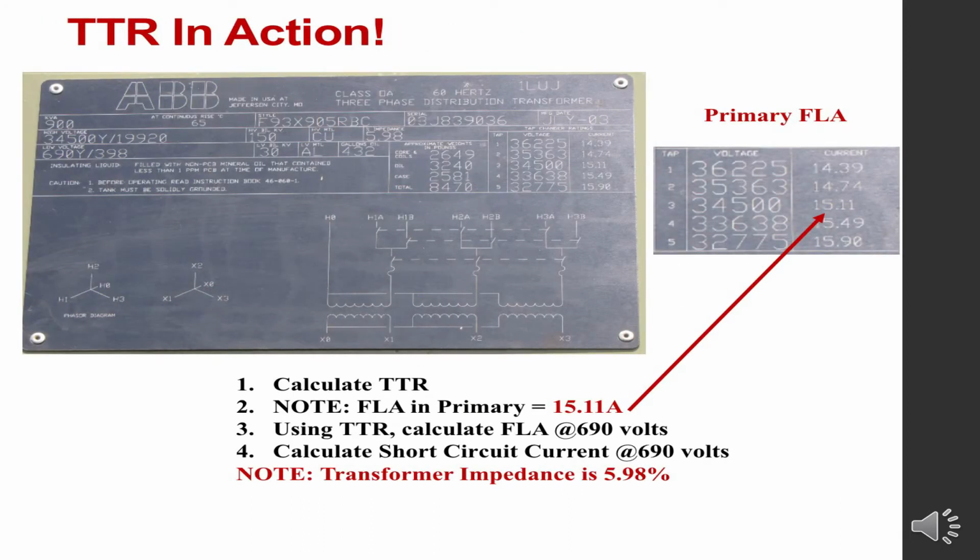Now here you see a transformer nameplate that illustrates something from an older transformer. First of all, from our previous discussion, if you look at the fusing on this transformer on the nameplate there, you'll notice there's only one fuse in this transformer in each phase. And that would mean that this has only expulsion fuses protecting the transformer. And as we discussed earlier, that means it's worse for you if you were to have a high voltage winding fault in that same unit. It probably couldn't handle the fault. Now, if you look in the little box in the upper right, they're even nice enough to calculate full load amps for you on the high voltage winding. So at 34,500 volts, this 900 kVA transformer will draw 15.11 amperes. So they're nice enough to give that value to you.